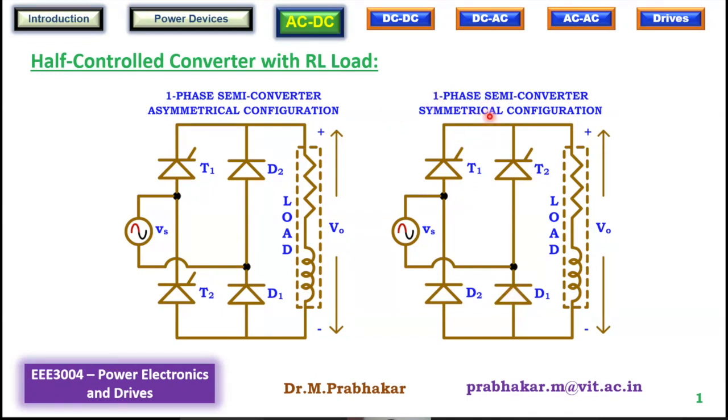But both configurations work in the same way. Meaning the output voltage waveform V0, or any other parameter, supply side parameter or the current through the SCR, nothing is going to change. All the circuit parameters will be exactly similar for asymmetrical and symmetrical configuration.